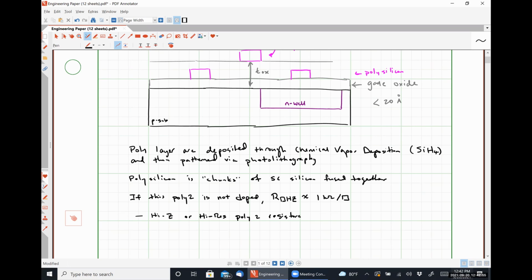It's only 25% higher than what the N-well itself gave us. And it's because the N-well is behaving like effectively single crystalline silicon over large regions. And the high res poly is single crystalline silicon over short regions. And so that mishmash of crystallography is what's giving it that increased amount of resistance. But other than that, there's really no difference between the two.